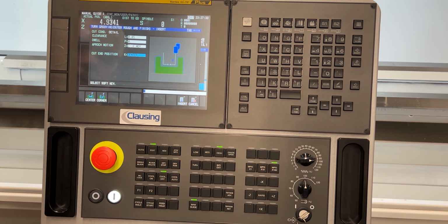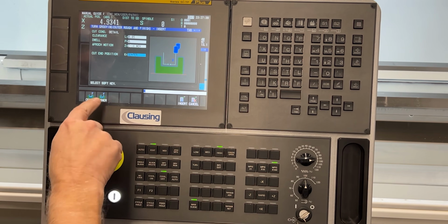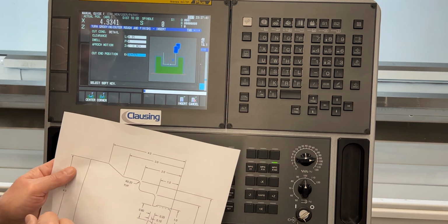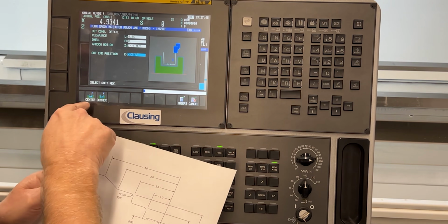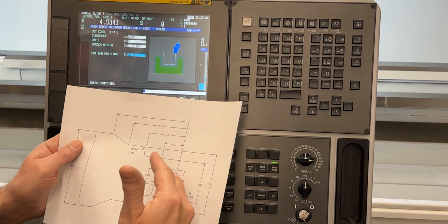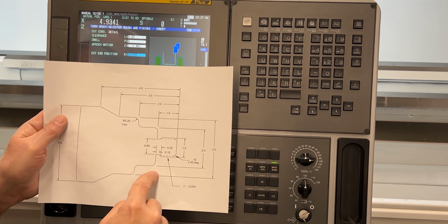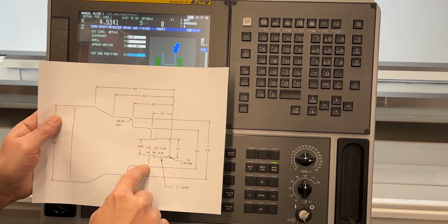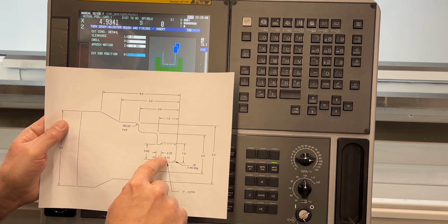My end cut position is for the finishing. So we have center or corner. On the center, because I'm going to have a radius back in that corner, I'm going to use that, because that way it'll slide down one of that angle and then slide over towards center, come back out, come over to the left side of the groove, come down and slide back to center.